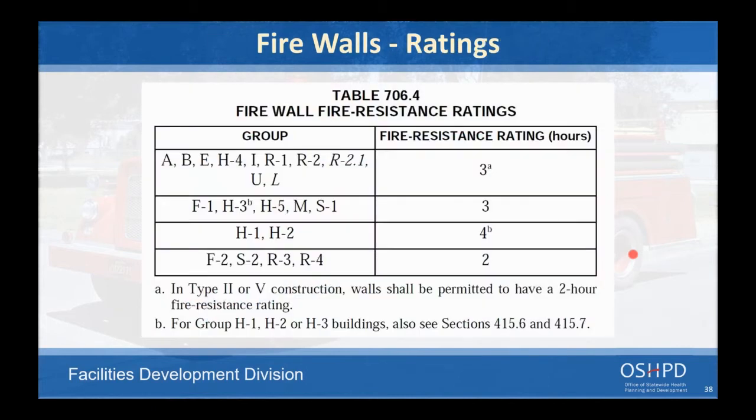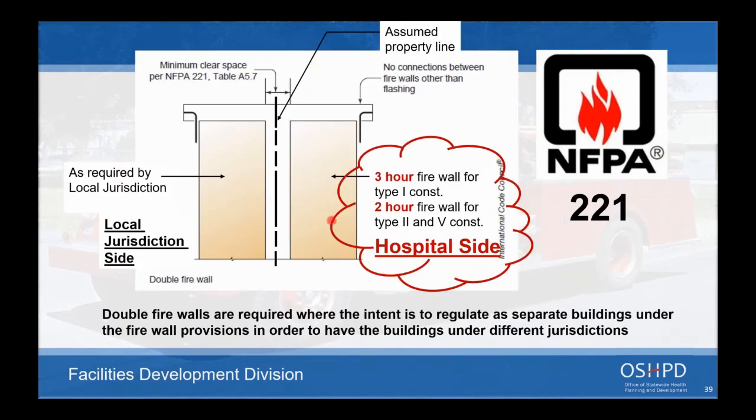So the fire resistant ratings, again, are based on occupancy, what's going on next door, and the fire rating must be on the hospital side. Now, local jurisdictions may have a requirement that it be on their side as well. So that's something to consider.